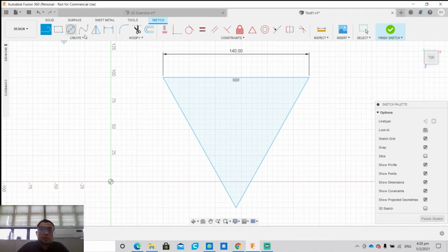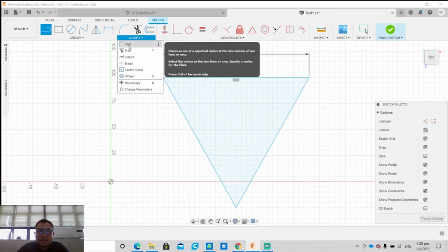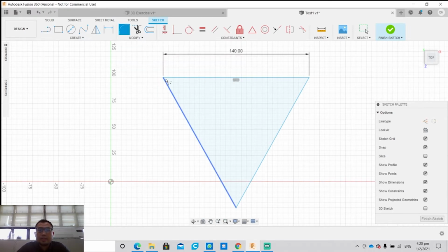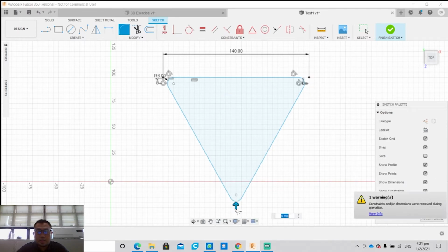All right. So now I think I would like to fillet the edges. All right. I do not want a deep fillet. I would say 6 is enough. There you go. And on the other point, I click again, the sharp edge, click, and you have those sharp tips gone. All right. So now it's done.